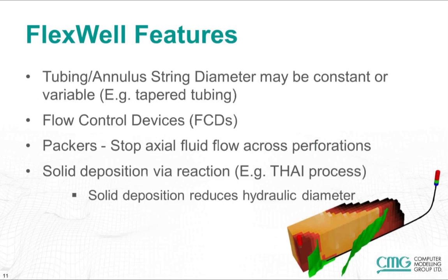In FlexWell, the tubing and the liner sizes may be constant or variable, such as the case of tapered strings. We can model flow control devices, packers which prevent axial flow across the perforations. We can also model solid deposition initiated via reactions such as coke deposition in the case of in situ combustion projects, and this solid deposition reduces the hydraulic diameter.